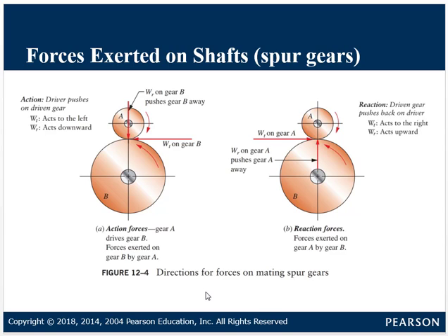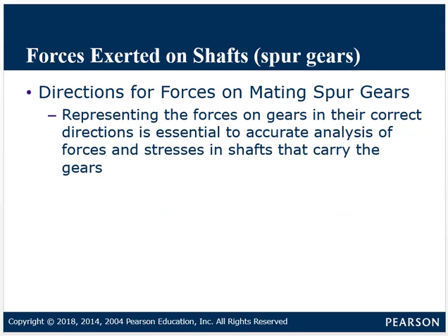It's very important that we get our load directions right, so when we draw our shear and bending moment diagrams, we're going to get the right forces in the right directions. So, directions for forces on mating spur gears. Representing the forces on gears in their correct directions is essential to accurate analysis of the forces and stresses in shafts that carry the gears.